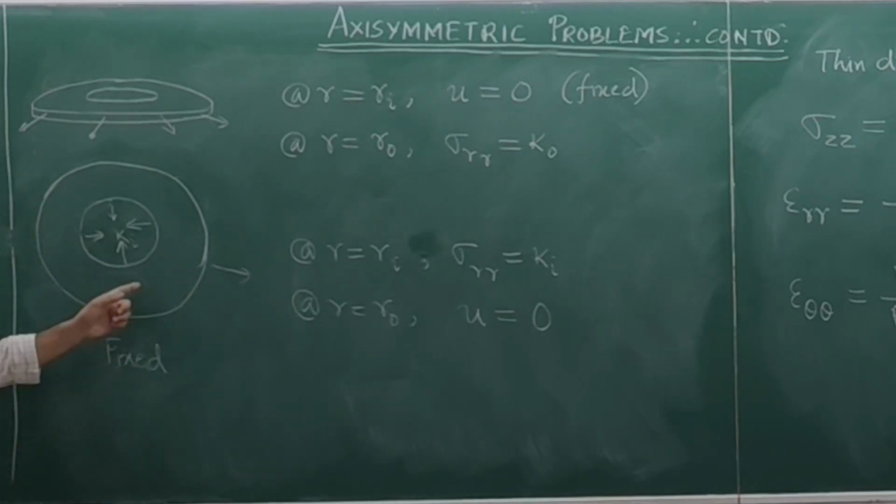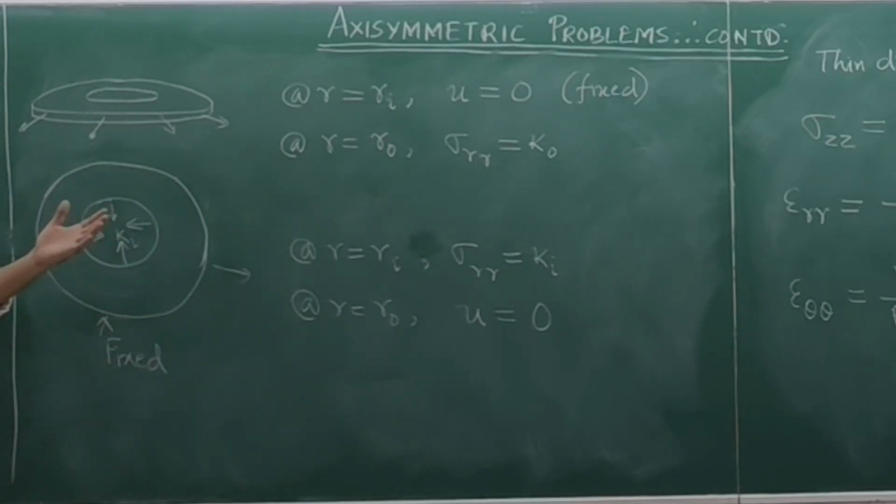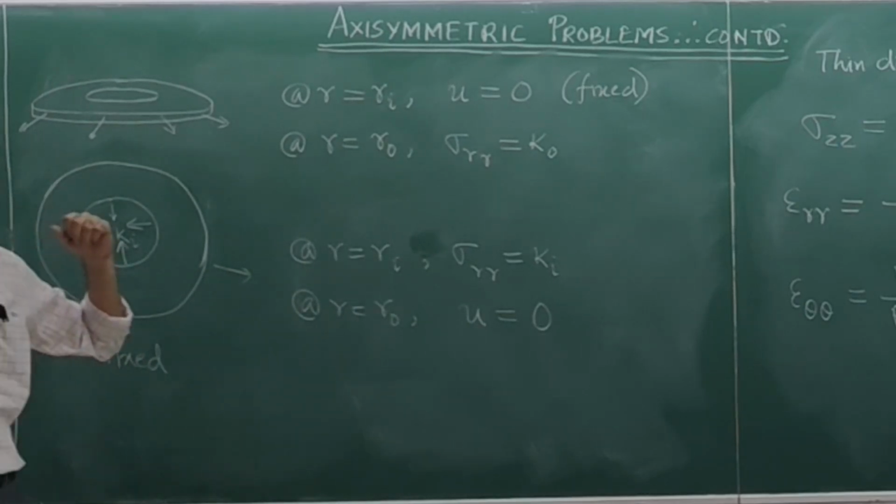Now, this is for the disk. You can have the exact same thing for the plane strain case also, for the thick wall pressure vessel. Exact same thing. Nothing changes, but of course your final expressions of the answers will change depending on whether it is plane strain or plane stress.